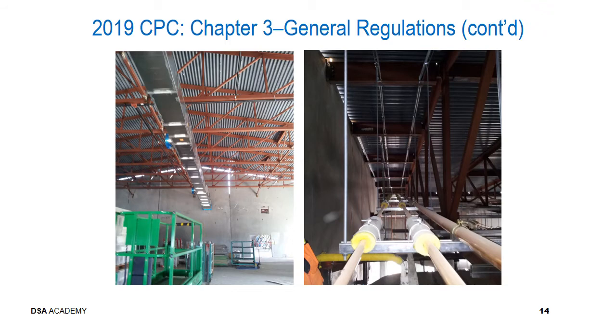Now, one thing to consider is you need to make sure that none of the joints that you're going to need to observe during the water pressure test are being inadvertently concealed by the insulation and the insulation protectors as installed. So that's going to have to be somewhat coordinated with the contractor.